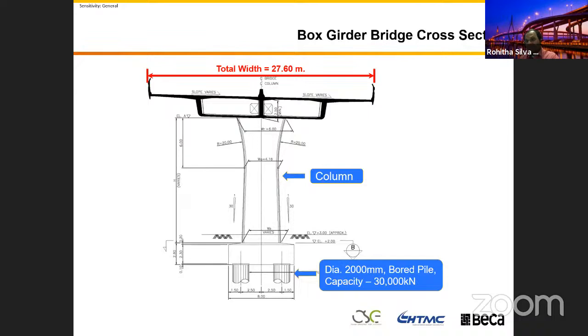You need to have them. I think you all have experience driving along flyover bridges. Every 25-meter span you've got a joint. You can hear a bang, bang, bang, bang all the time, right? Even the road authorities have a headache as well. Their design life is 30 years, but you have to replace them before even 15 years, because it's very difficult to manage. It's really inconvenient for road users as well.